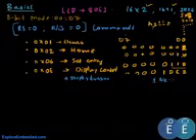If it is 1 it shifts the display, and if it is 0 it shifts only the cursor. Now the next bit is right or left. If this is 1, it shifts towards the right. If it is 0, it shifts towards the left, and these two bits are don't care.